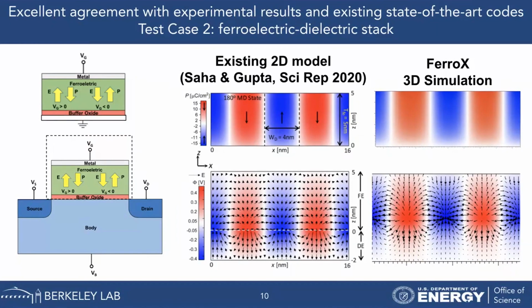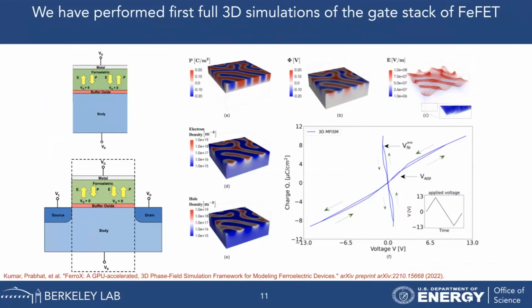And for this, we compared our results with published work. It is from 2020, and we have excellent agreement on that as well. All right, and finally, we did the first full 3D simulation of the entire gate stack. So we have ferroelectric, dielectric, as well as the semiconductor layers.